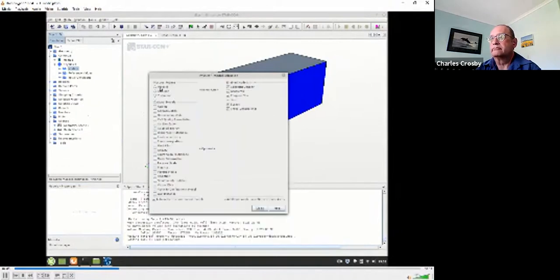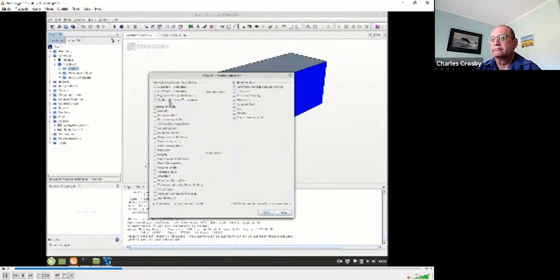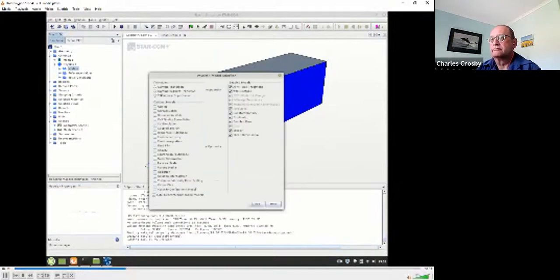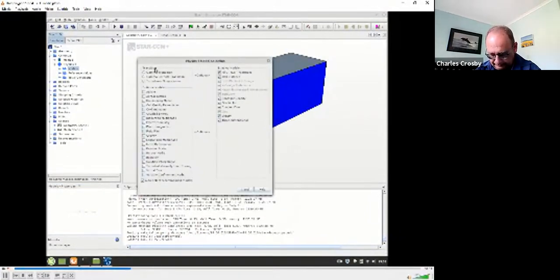We'll use a constant density gas, and we'll use a turbulence model, and we're selecting a K omega turbulence model. By default, it selects the SST K omega model, which we've discussed before as a good general purpose choice. We don't need any other models. We can work with this one.